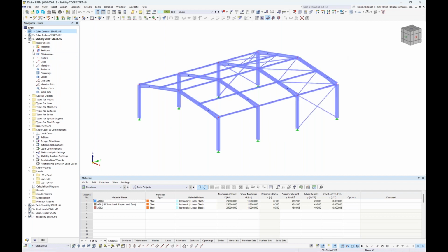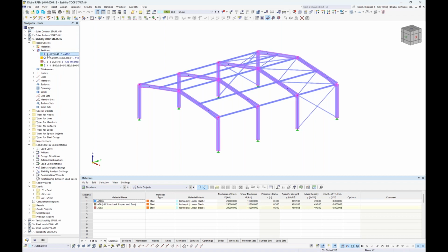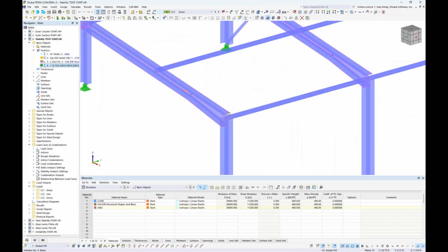If we want to do a quick overview, the cross sections are from the AISC database. So we have W10x49s. We have some square HSS sections spanning between these moment frames, single angles for our cross braces, lateral bracing. And we also have a very small taper for this beam member. In particular, this is at 25% of the member length before it frames into the vertical columns.